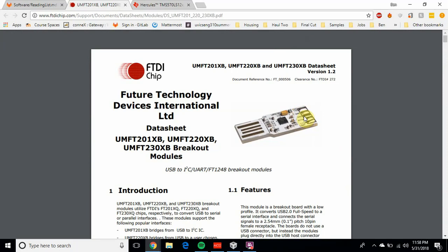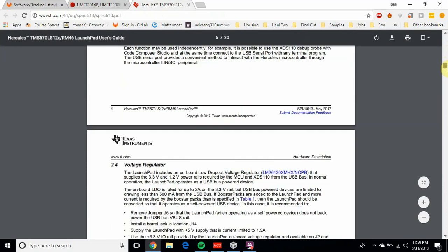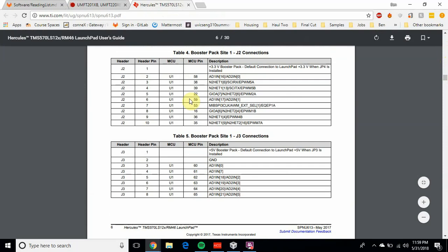We're using the UART protocol, and essentially what that necessitates is a single data bus, which is the wire itself, to pass on information through a receiving pin and a transmitting pin. Those are the 2 major connections you need for this SCI setup, as well as a grounding pin for obvious reasons. So just quickly, we're going to reference our TI data sheet and see where exactly those pins are on the board so we can connect them up properly. First we'll start with ground.